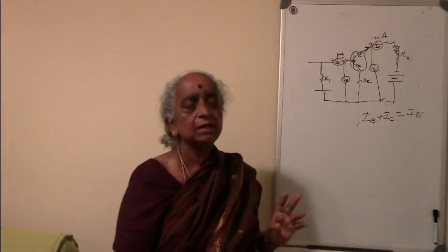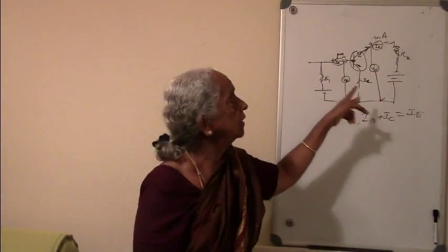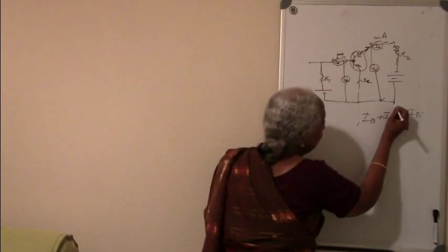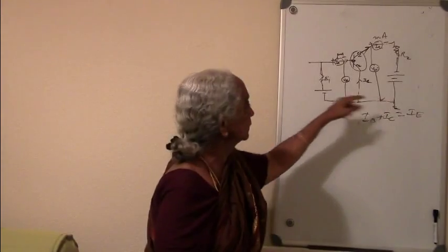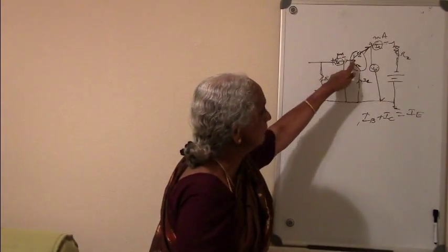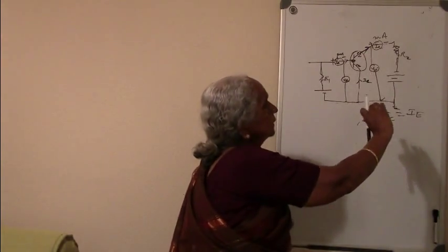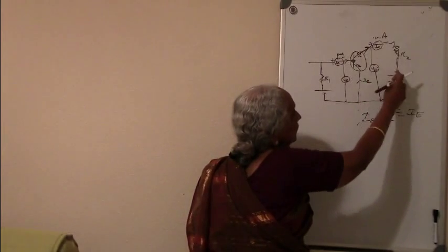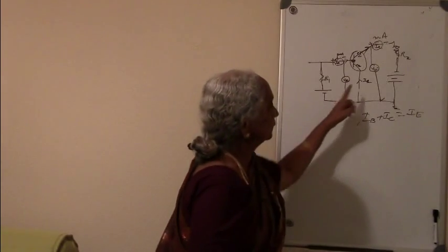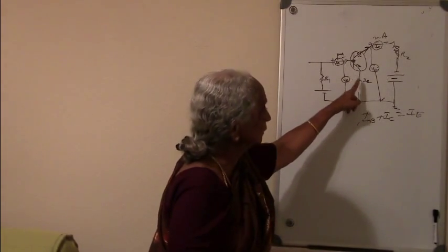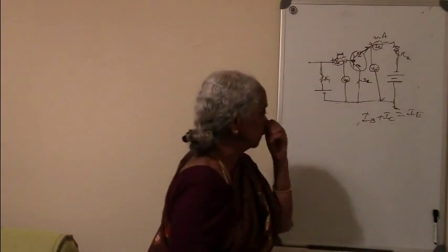as the output side. And collector being the common terminal in the common collector mode, that should be grounded here. And then because the base has to be forward biased, you connect the positive to the base, P type of base. And because the emitter also has to be forward biased, it has to take its lead from the negative of the battery at the other side. And as far as the collector goes, it has to be heavily reverse biased. The N type of collector should take its lead from the positive, only then it will be reverse biased.